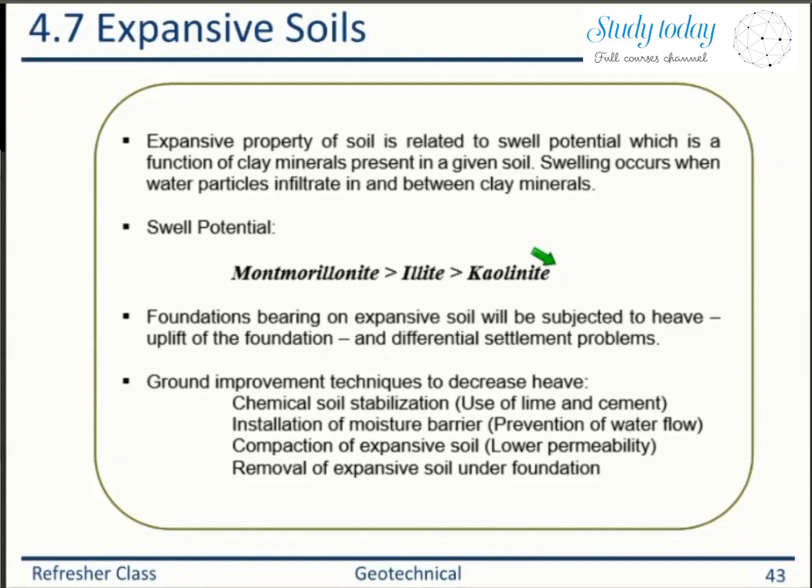There could be flood. If your soils have clay minerals come in contact with the water, then your clay soil will expand, right? So that will push your foundations, your roadway, whatever structure is above it, it will move up. So you don't want that to happen, right?